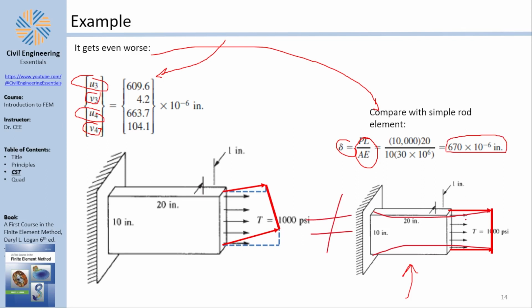Of course, the bar would elongate, and this is a simplification, by the way, the bar would elongate the same everywhere, and the bar would become thinner due to Poisson's ratio. You studied that in Poisson's ratio. If you have a longitudinal extension, the bar gets thinner, and if you have a longitudinal compression, the bar gets thicker.